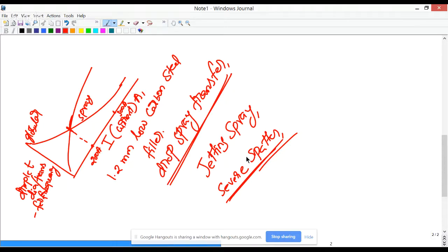And so why is the cementite precipitation retarded? Because the cementite lattice cannot hold silicon and aluminum. Okay, so they have to be pushed out. So the low solubility of silicon and aluminum in cementite is the main reason why these elements retard the cementite formation.